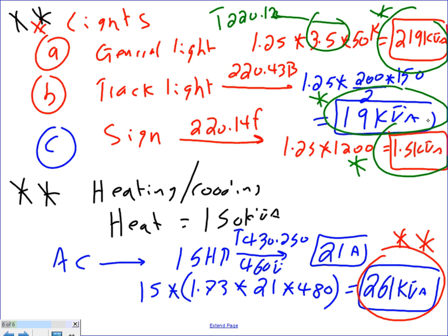I just converted the horsepower into volt-amps because I need to compare apples with apples. I can't compare apples with oranges. I can't compare horsepower with kVA. You have to convert the horsepower to kVA so you can compare. If both of them are horsepower, it's so easy. And then you also have to convert them from horsepower into kVA so you can add them to kVA. I can't add 3 Chrises and 2 Chets. That doesn't make 5 of anything. You have to add a different gender to make people. So 745 watts per horsepower.